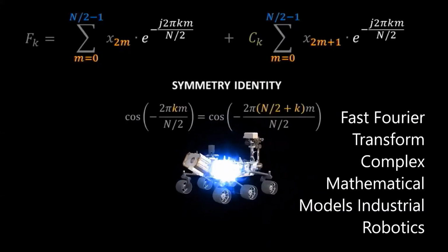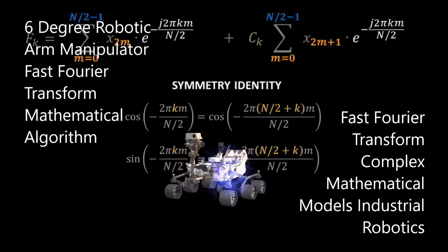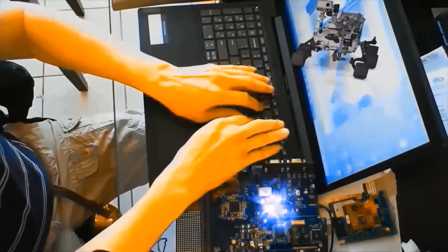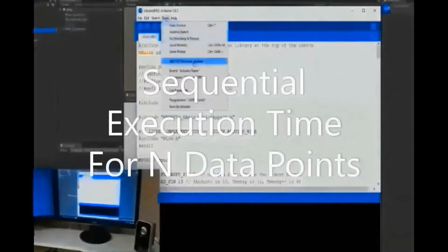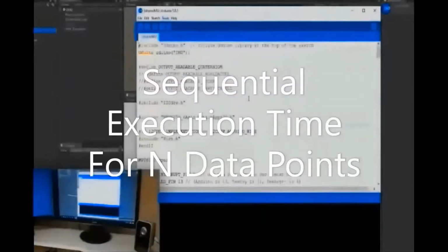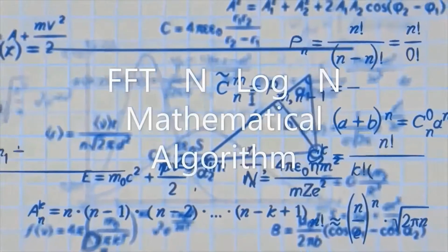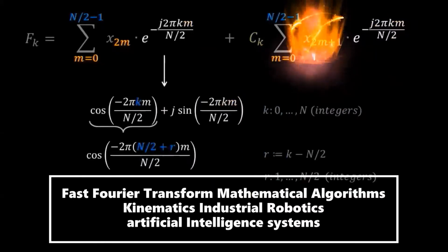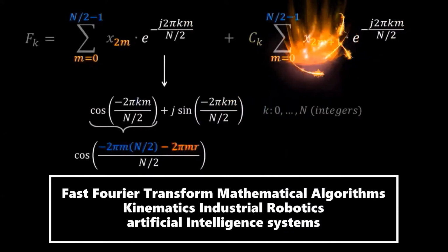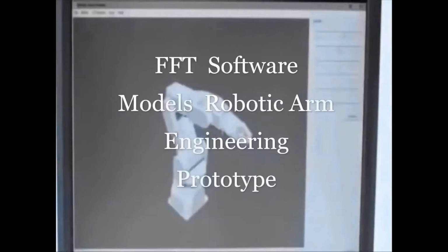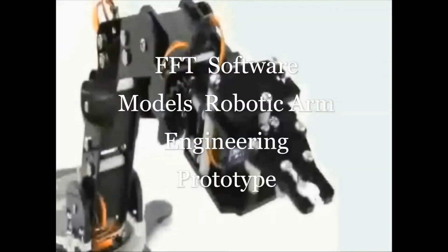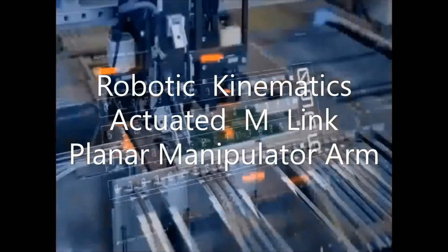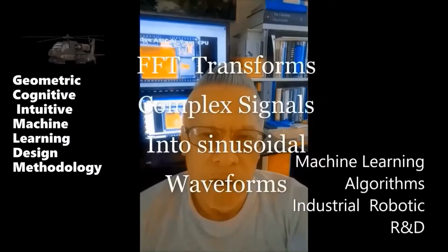Real operations requirement in FFTs. A complex addition can be implemented as 2 real additions. Generally, a complex multiplication can be implemented as 3 real multiplications plus 5 real additions. In the case of the fast Fourier transform FFT, use of efficient radix-2, radix-4, or radix-8 algorithms can be used to reduce the number of non-trivial operations required.